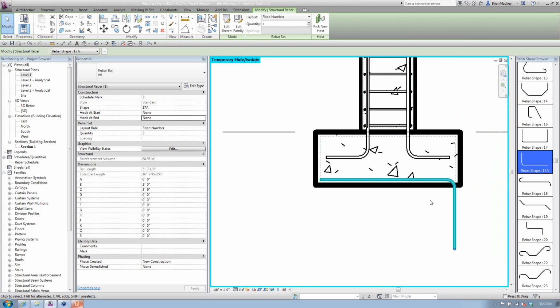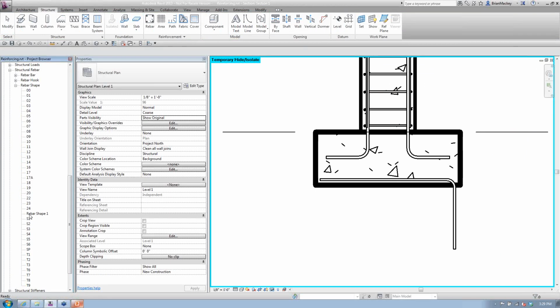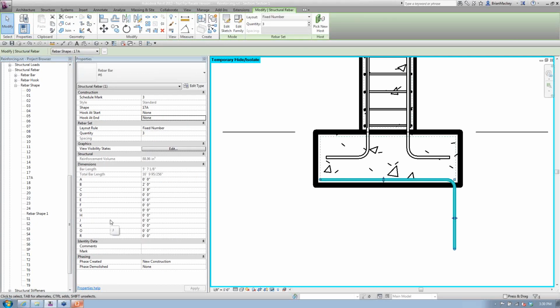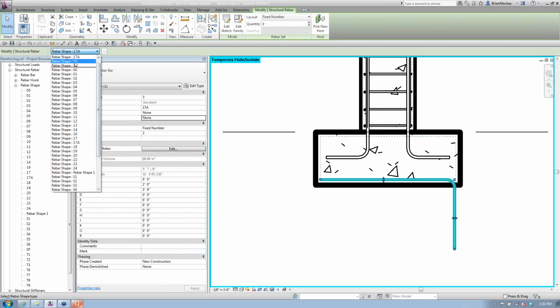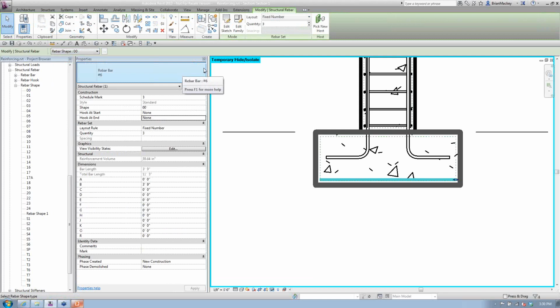So just be aware of that as you start doing this. I go to projects and I start looking down at the family types, and I start looking at the rebar shapes, and I'll see rebar shape 1, 2, 12, 256, simply because people are turning the hooks on and off. So I always like to point that out because that can become an issue. You end up with hundreds of different rebar shapes in there. So think about that. Change the bar type as opposed to necessarily doing the hooks, if that's something that you were looking at doing.